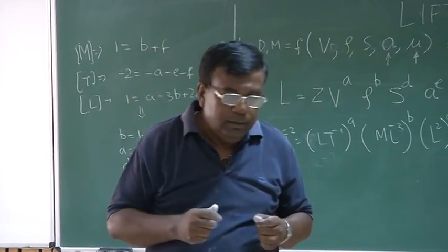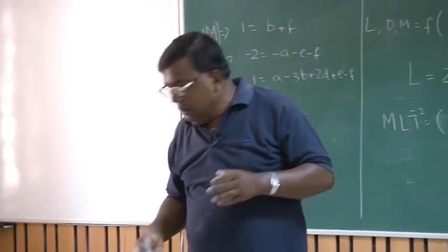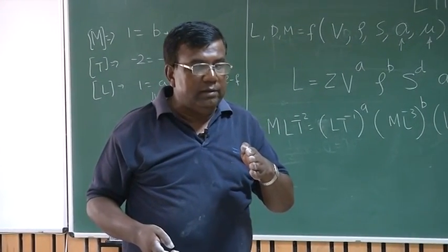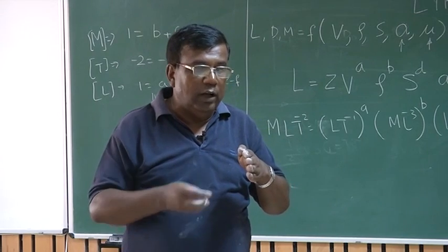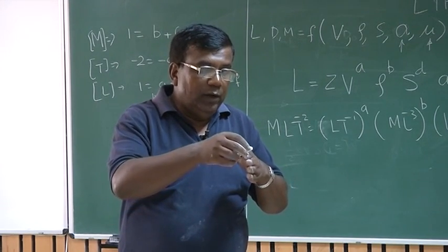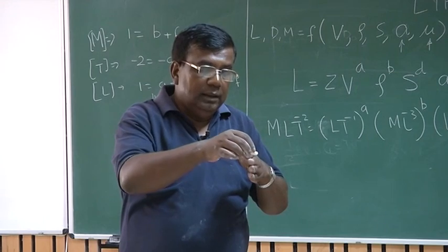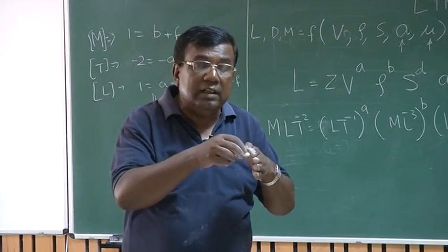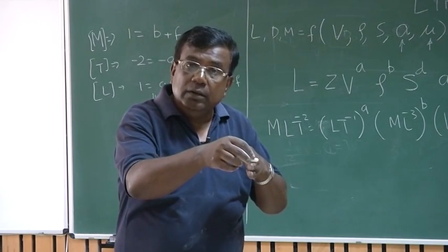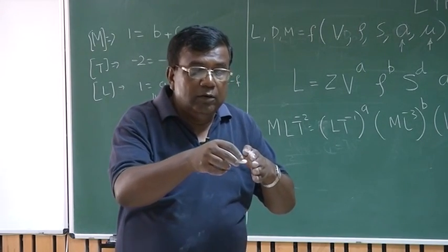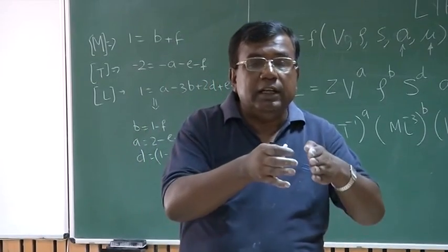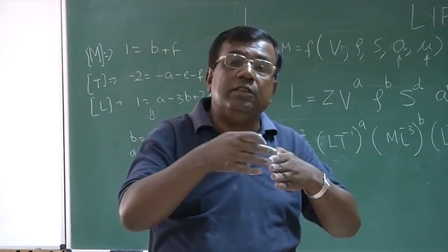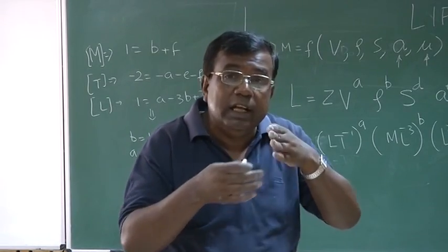Now think of, suppose there is a body moving like this, and the speed of this body is less than the velocity of sound. So what will happen? Before the body reaches another particle, this disturbance will reach there earlier than the body, because the body speed is less than the velocity of sound. So when it moves, the particles will arrange themselves based on the disturbances they have already received before the body has reached there.